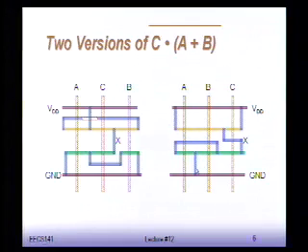So if you work this out, it turns out that the right thing to do is choose this node as the source of A and B and connect it to ground. And then these other two extrema are going to be the drains of B and A. And you need a piece of metal to connect them together too, because otherwise they will not be connected together. And then this also happens to be in common with C. So we know that this is the intermediate node. And therefore, the output has to be the other node that is tied to C, X. Okay, you can imagine that for this particular example, doing this was easy.